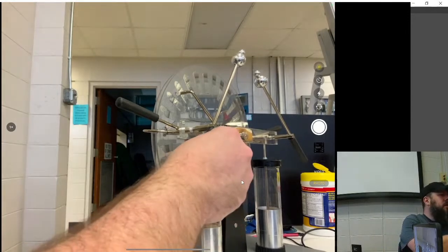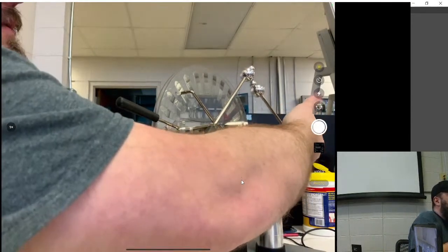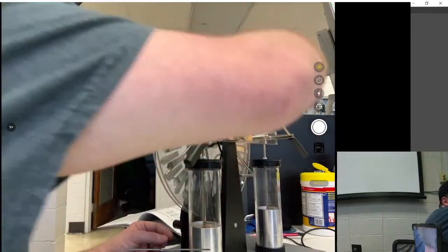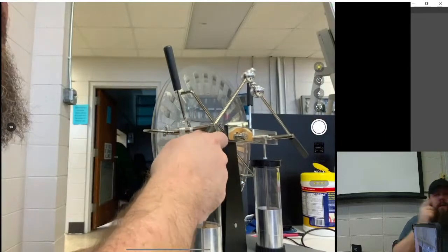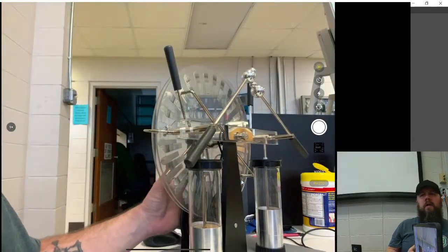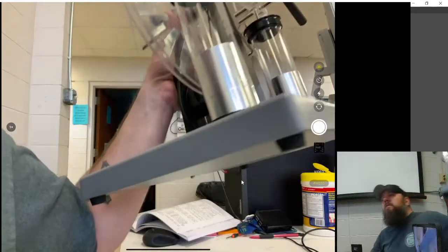All right, now this will pop you, and it will keep a pretty good charge on it. So you want to kill the Leyden jars, and you want to put these together so that any built up charge can dissipate. Okay.